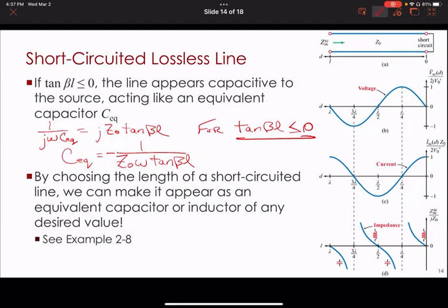That's going to be at the types of frequencies that we're talking about here. It's going to be, you know, a gigahertz, maybe up to tens of gigahertz. It's going to be in the realm where transmission line concepts are important. If you're dealing with the software behind it, or you're dealing with the digital circuits, you probably don't need to worry about this. But if your job is the one to deal with the antenna, or the connection from the antenna to, on the receiving side, let's say a filter, amplifier, all of these things before it gets converted to digital, where now it can go into the processor and you can do all your magic, right?